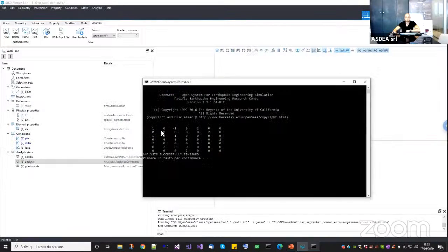And another thing that I want to show you is that, for example, here I have my original matrix. So 1, 1, minus 1, minus 1. Then I have this row and this row, and this column here equal to 0, related to the y degree of freedom of my model. And then for each constraint, I have a bound matrix. For example, here I'm saying that the x displacement of node 1 should be equal to 0. The y displacement of node 1 equal to 0.